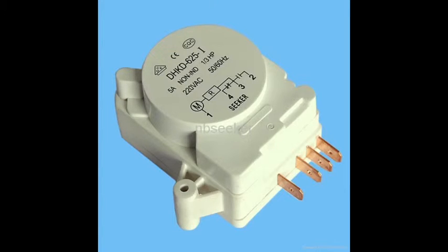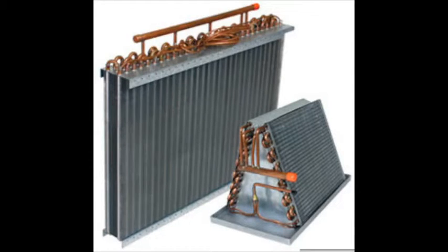An evaporator is a refrigeration coil that boils low pressure refrigerant, absorbs heat from the return air going across the coil, dehumidifies, and adds superheat to the refrigerant in its evaporator phase. That is an evaporator.